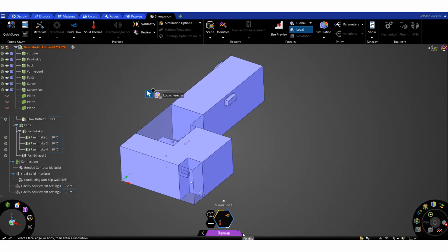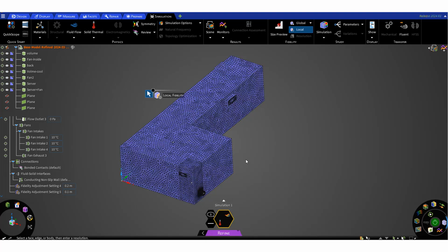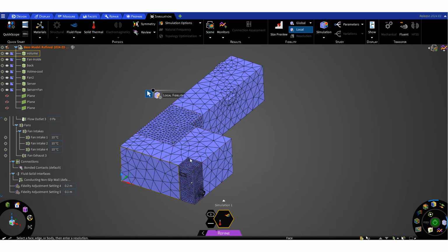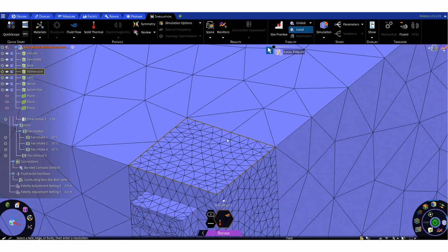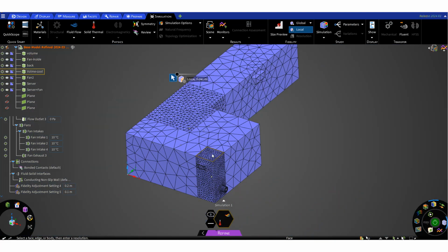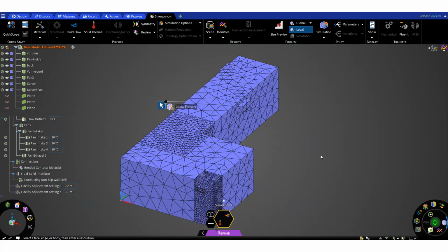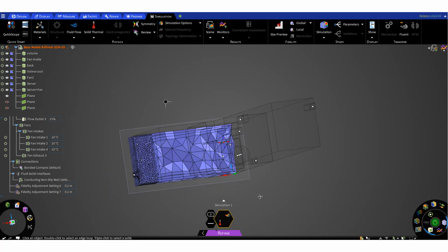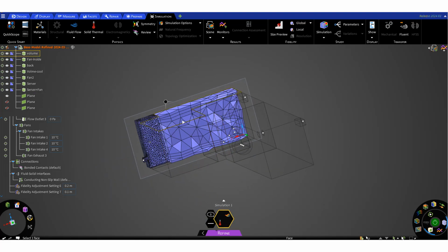We have very high fidelity. We can decrease that. Okay, if I decrease it, maybe it is easier. Now it is better to visualize the different sizes of the elements for the mesh in this corner and in here. Let's check the mesh inside. I section the domain. We can see the different sizes we have in this corner and on the other side.